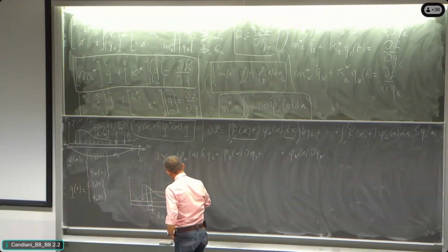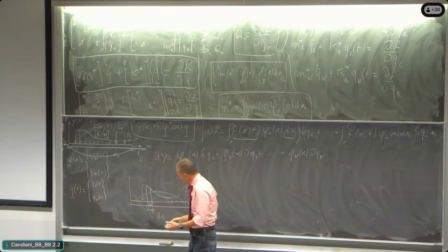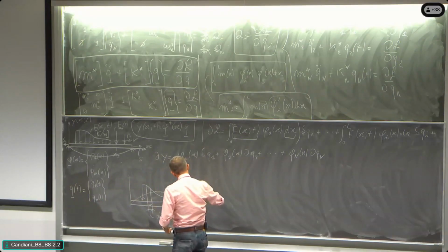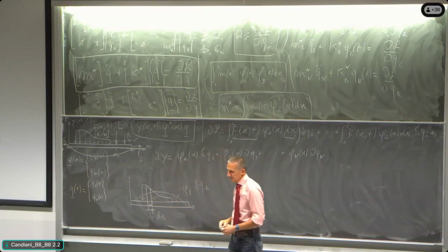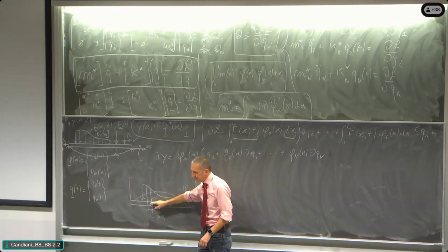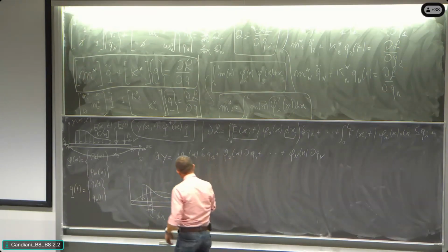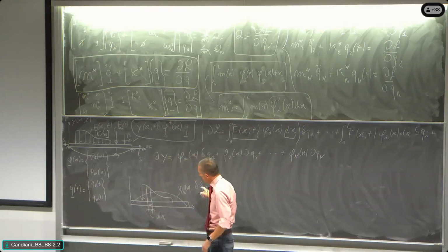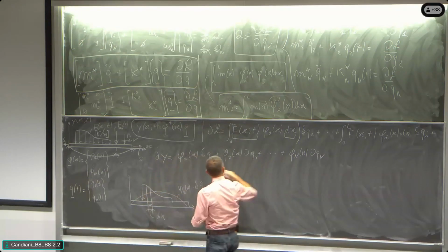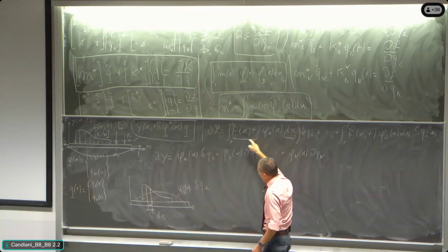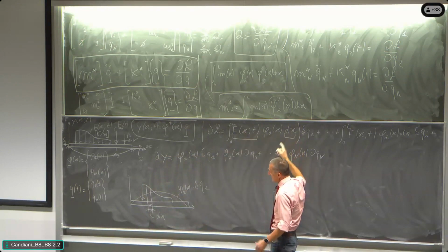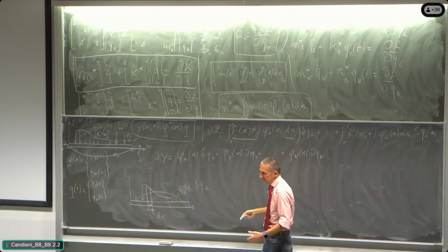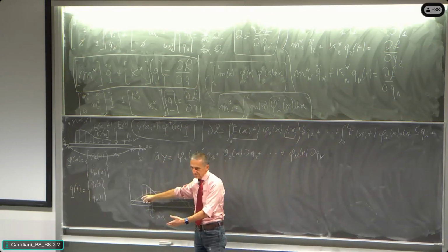This mode is phi1, and so I am moving it times delta q1, all right? And so looking at the mode 1, I am making it move by the quantity phi1 function of x multiplied delta q1, making it work through the force at the same location x multiplied by dx, but I have to extend all of that to all the distribution of the force.